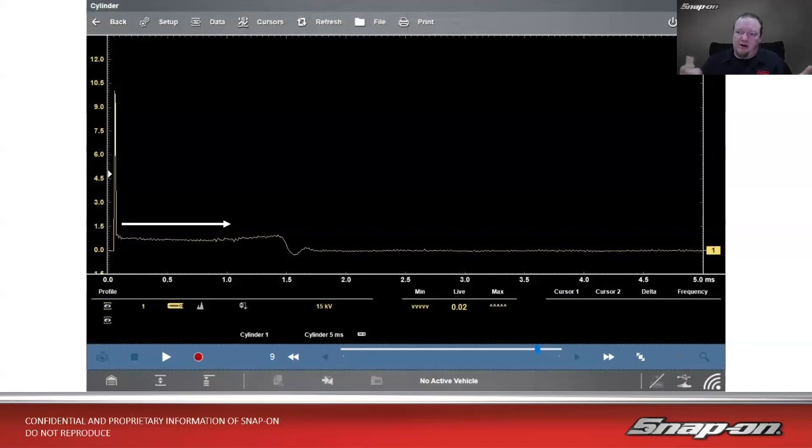So if I look at this spark line, it's on a different car. This is on one with a spark plug wire, and we can see it's fairly flat. This is a normally operating vehicle, runs perfectly fine. I see a little bit of turbulence in there, nothing major. Overall, it's pretty flat and a fairly efficient coil, with only a couple little oscillations down there at the end.